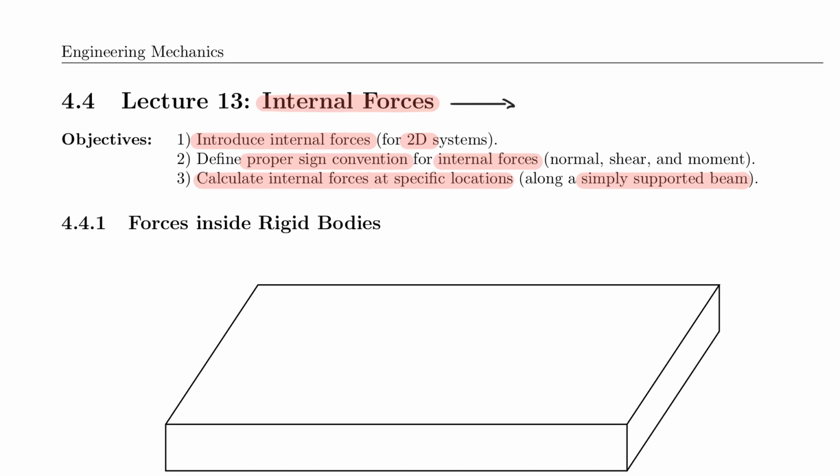and let's first understand that these internal forces that we are talking about today are really forces that act inside structural members, right? So forces that act inside structural members. And effectively, that means that this is the force that keeps the rigid body together, or the structural member. So it's the force inside that keeps everything together. You may think of this as the glue that holds everything together inside a particular rigid beam.